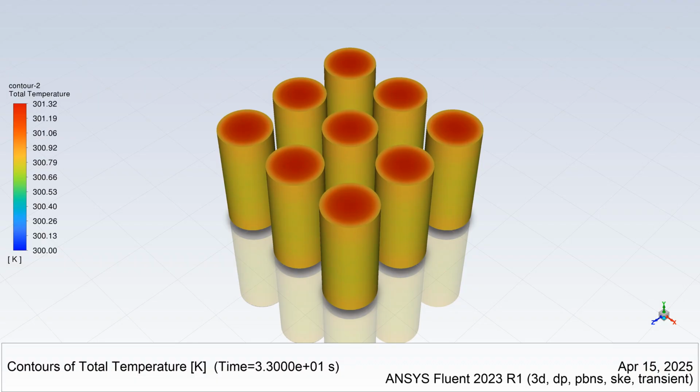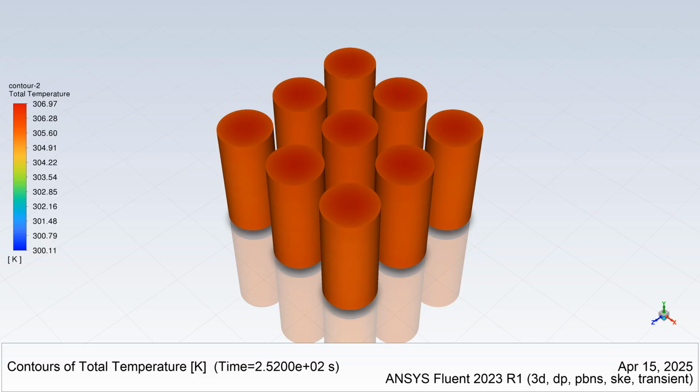So this represents the cell temperature, how the cell temperature varies with respect to flow time. So that is now visible. As the cells are surrounded by casing and the casing is surrounded by PCM, the PCM will take heat as soon as possible till the time when it reaches the solidification and melting point. So you will see 309.50 as of now for a flow time of around 400 seconds. So till around 1200 seconds, this value of temperature may slightly change.